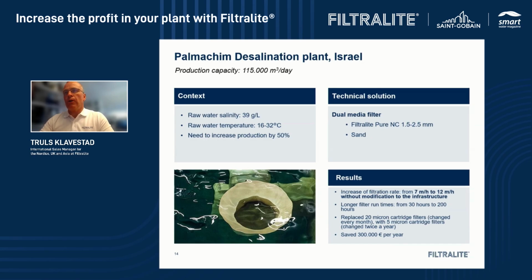For sure, they got less biofouling in the RO plant, which gave them less cleaning of the membrane. Less cleaning of the membrane increased the lifetime of the membrane, which was very important for them.